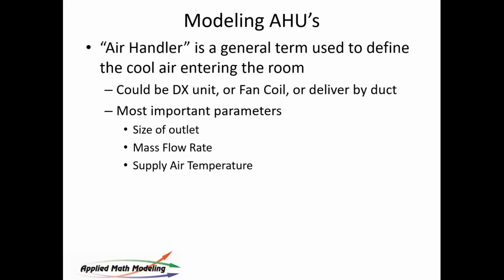It can also be delivered by duct. It can be the outside air. In mining currency applications, they're often using free air, so they're just pulling air in, often through an evaporative media, into the data center. It doesn't really matter to us, because what we're concerned about in this analysis is the delivery of air inside the room. So what matters most to us is the size of the outlet.